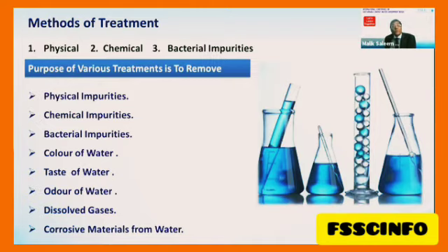If you have process water for boilers, high pressure boilers, we require ultra pure water. If you require it for medical or pharmaceutical purposes, every process requires a different type of water, and your designer or the consultant or the contractor has to supply the equipment as per two requirements. One, what type of water you are having, and the second, what is your required quality for the process. That required quality is given to you by your machine supplier or the process developer.